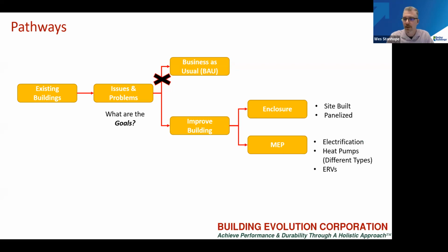Well, we can use those replacement time periods as opportunities to improve the building, and it's incremental improvements over time, where we can improve it for the enclosures, where we could use site-built improvements. Say the cladding has to be replaced in the building. Then you could do exterior insulation and then cladding over it, or a panelized approach.